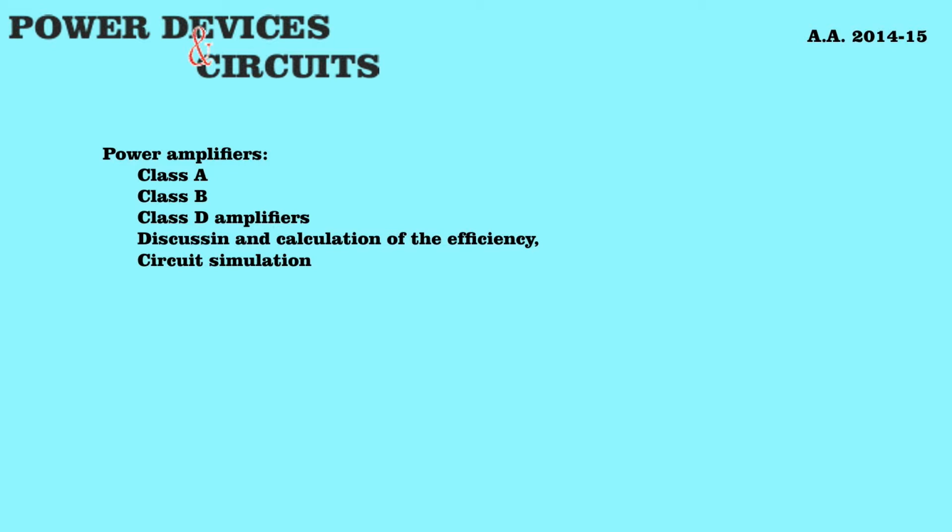The maximum power dissipation in the circuit is obtained for 0 power on the load, PL equals 0. The polarization power is constant, we calculated it, it's VCC multiplied I0. In the end, the maximum power dissipation on the device will be PS minus VCC I0 is equal to VCC I0, that is 50% of the entire power. Remember that the maximum power efficiency is 25%.